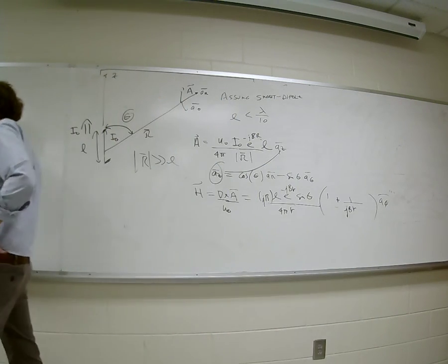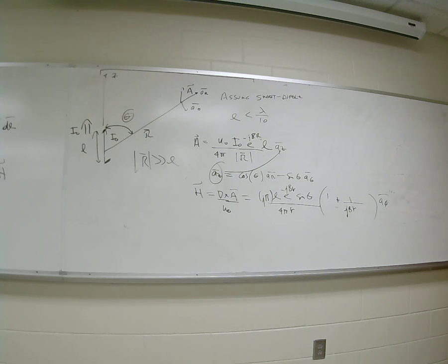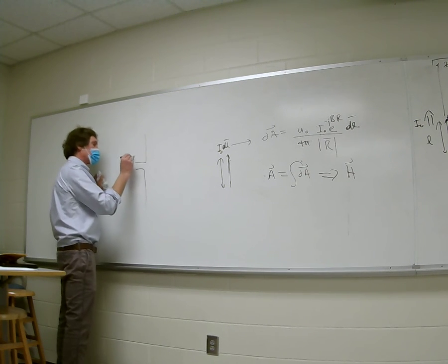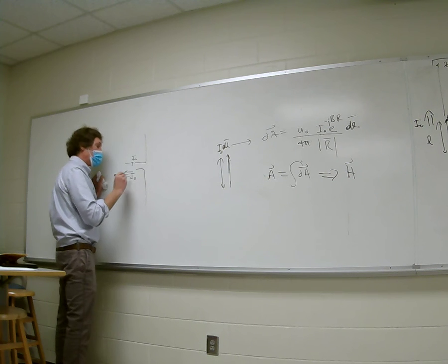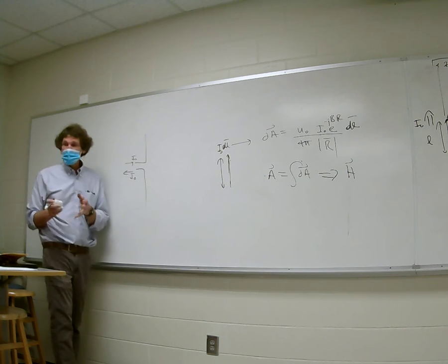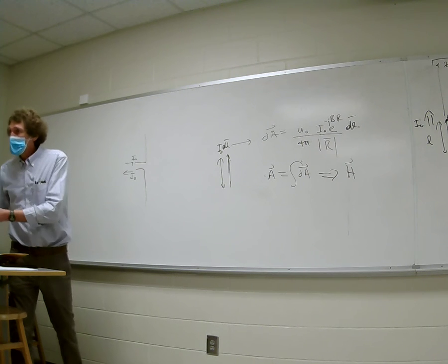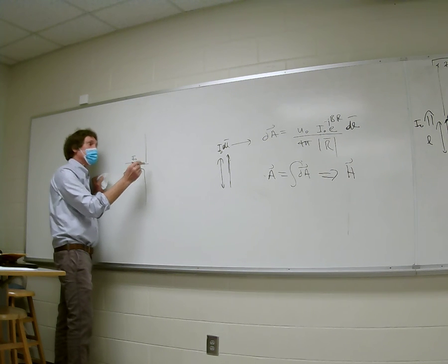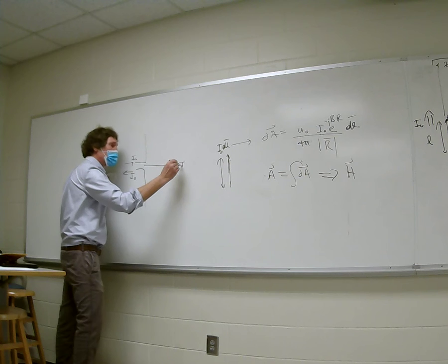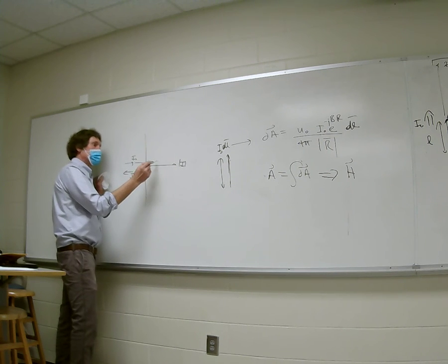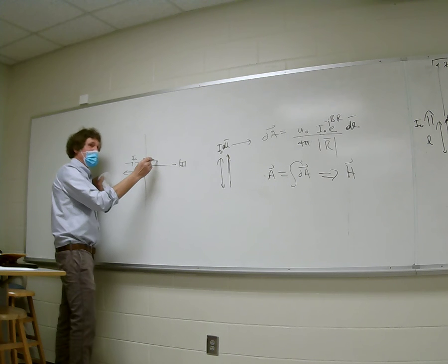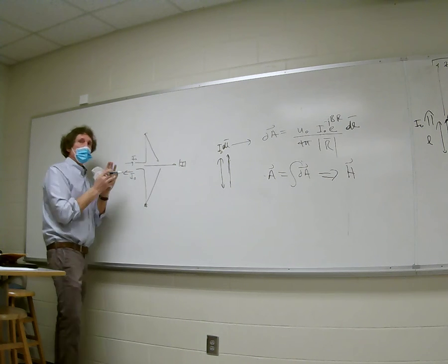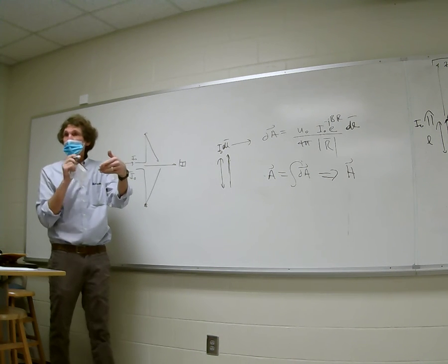Because if you have current flow in a wire, and I need to tell you this so you understand it. If you just take a look at a wire antenna, you don't have to write this down, just listen. If I'm feeding it with a current I naught this way, then a current I naught that way is coming out of the bottom. It's called a differential feed. Does that make sense to everybody? With me on that? All right, current going in, coming out. What actually happens is, if you looked at the magnitude of the current here versus distance, it would start out at a peak, and even for very short dipoles, it'll start doing this. It has to go to 0 at the ends, because we know current can't be a constant value and just stop, because then you get charge accumulation.